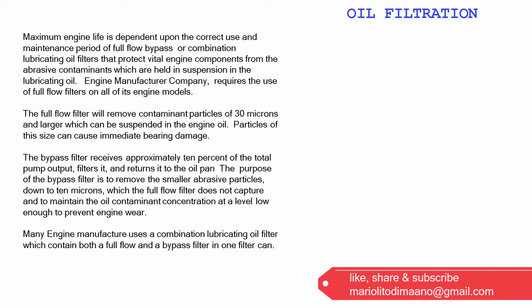Maximum engine life is dependent upon the correct use and maintenance period of full-flow, bypass, or combination lubricating oil filters that protect vital engine components from the abrasive contaminants which are held in suspension in the lubricating oil. Engine manufacturer company requires the use of full-flow filters on all of its engine models. The full-flow filter will remove contaminant particles of 30 microns and larger which can be suspended in the engine oil. Particles of this size can cause immediate bearing damage.